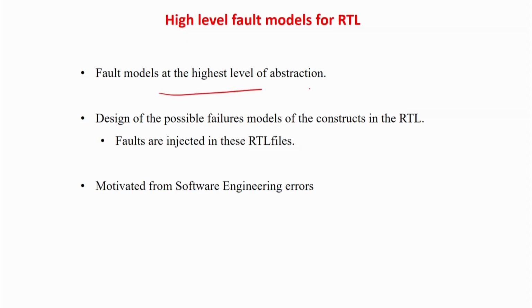These fault models should be at a very high level of abstraction, and the design of fault models should be very coherent with the constructs of the RTL, as the faults will be injected in the RTL file. That is, you should not have gate level or transistor level business when you are talking about RTL level models and testing. This should be very similar to the faults which can be embedded in the RTL.